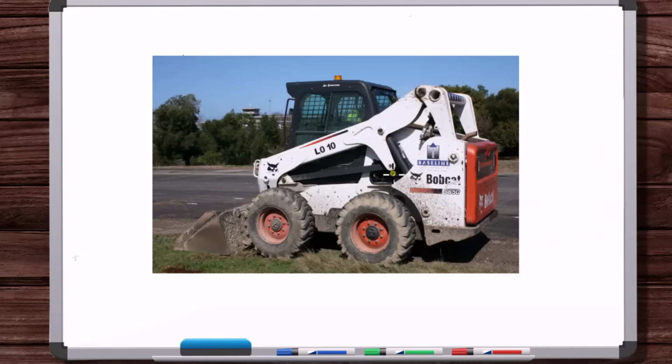And so if in that snapshot it was not moving, the velocity was zero, then when we apply all of the forces on the free body diagram in empty space, it shouldn't be moving, if we applied the exact load scenario that was present in that snapshot, right? If the component was accelerating at that snapshot, then when we apply the loads in empty space, the component should be accelerating just like it was at that snapshot. We have to apply all the loads. We can't miss a load.